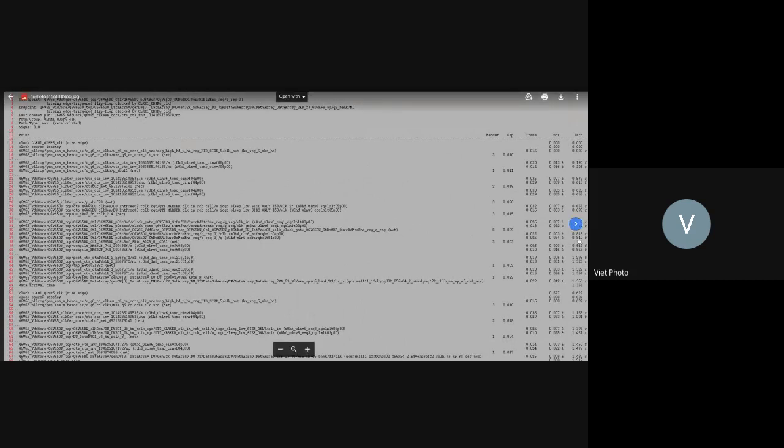So from now, the real data path is from that Q pin all the way to the endpoint, which is the CSN pin of the memory, right? You go here and then at the end it's here. After that, the total arrival time is 1.366 nanosecond.